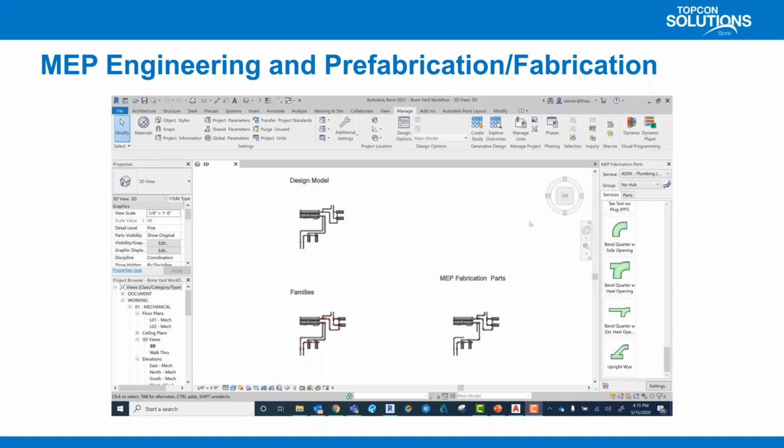Now, I've also seen different workflows for maybe extending conduit if we know that this slab is adjusted and we need to actually take our conduit up on a certain floor up 6 inches or 4 inches, what have you. Normally grabbing everything and then trying to adjust it up would be annoying. You can grab every element, maybe every floor of the project, and use Dynamo to have it adjusted or add in different types of connections, converting fabrication, you name it.